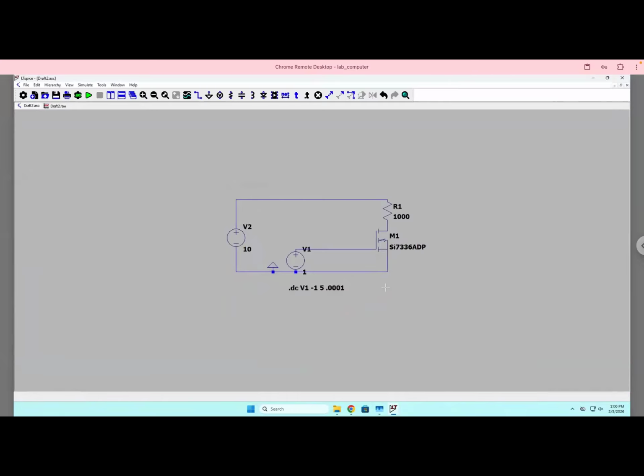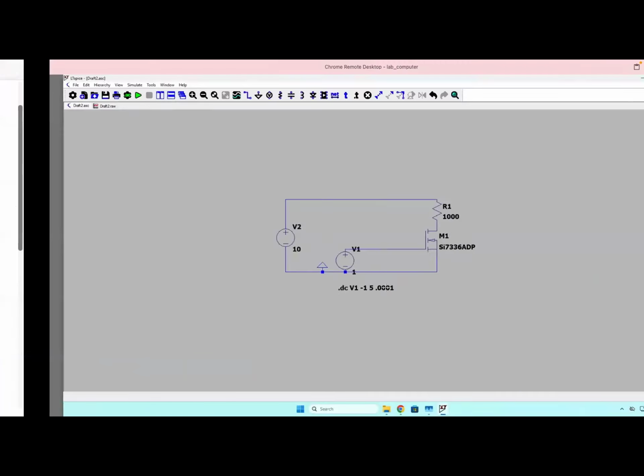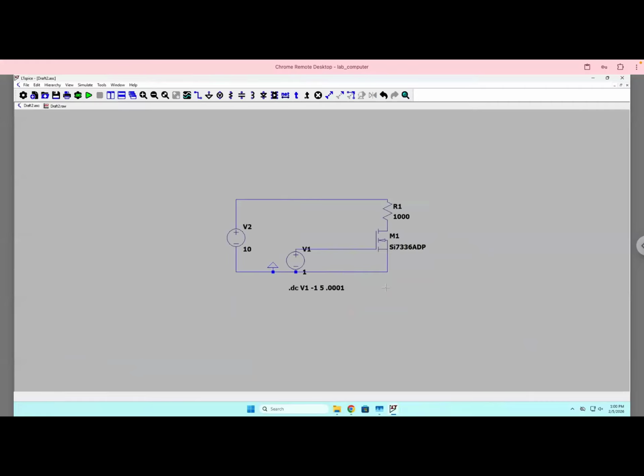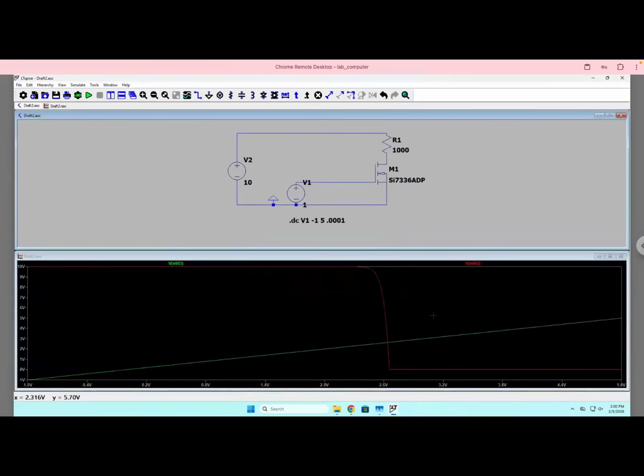That's all right. We can just use this MOSFET. We're just gonna have a really, really small input voltage range, which will be kind of funky, but it should still work. So from here, we're gonna want to take away the voltage that we got from the graph, and input that into the bias resistors, which are the ones I was talking about yesterday.